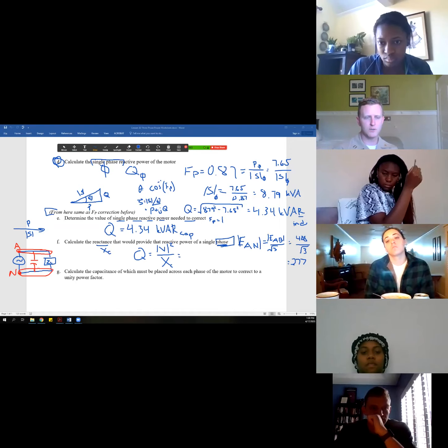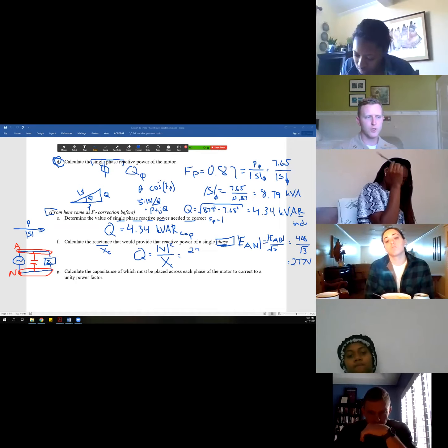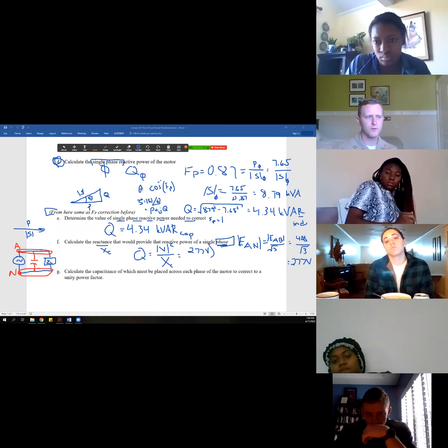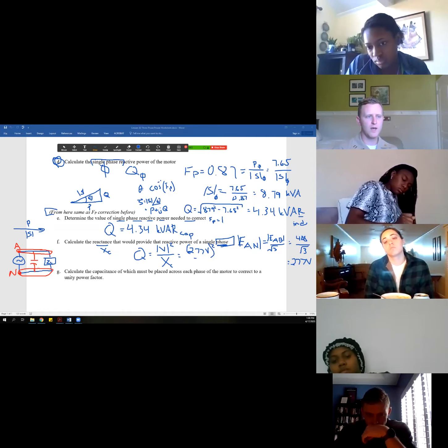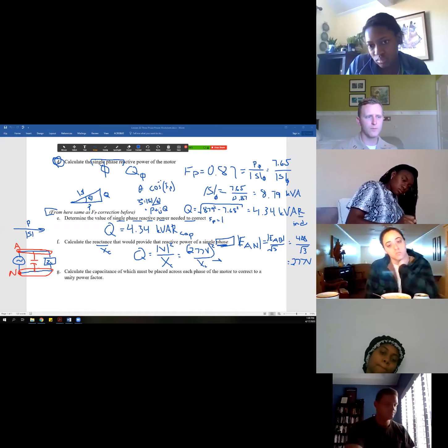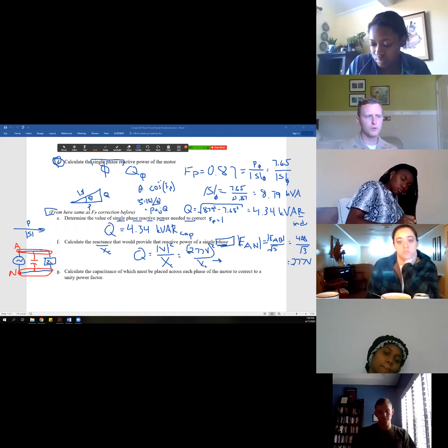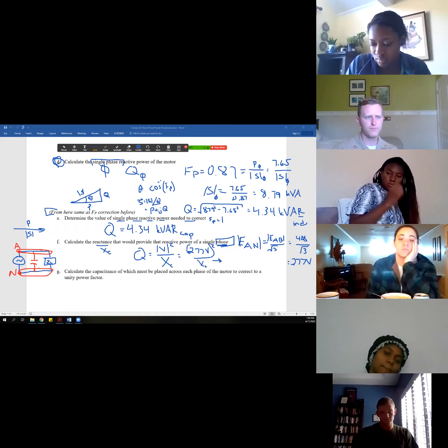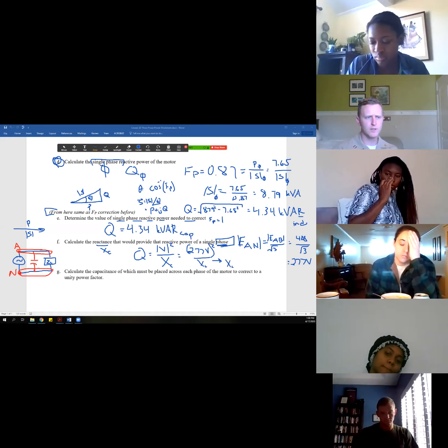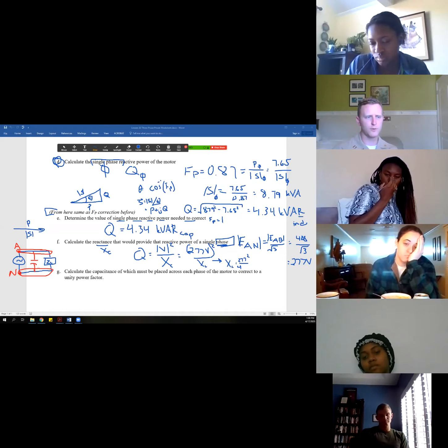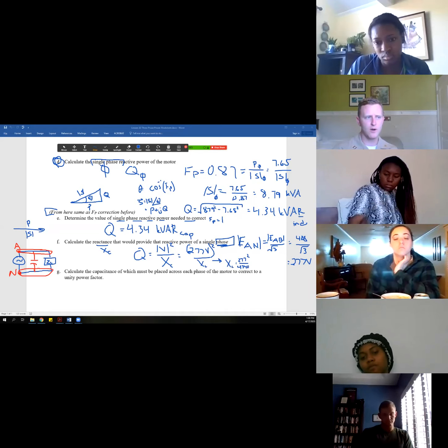So EAN comes out to 277 volts. So I put 277 volts, square that, and I solve for XC. So this Q was that 4.34. So X sub C is 277 squared divided by, it's really 4,340, because that was kVAR.